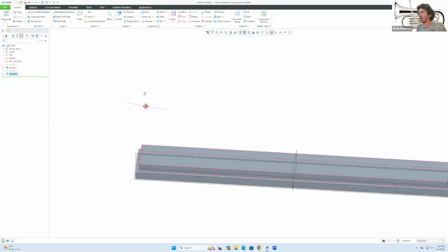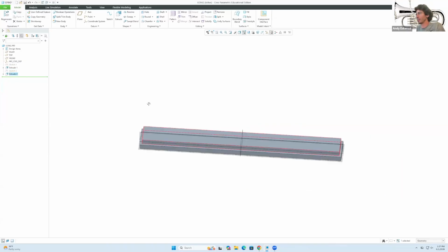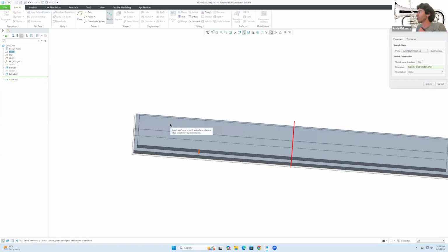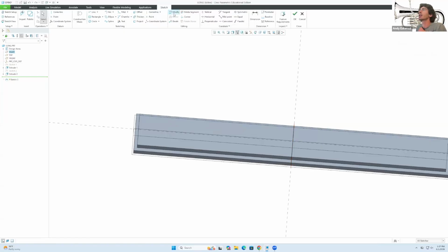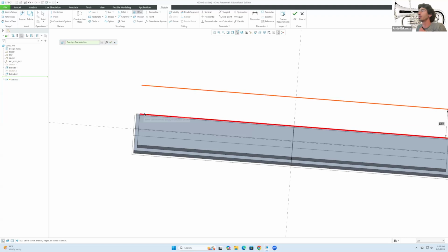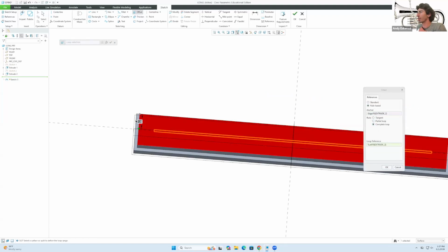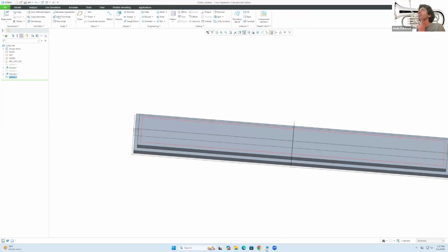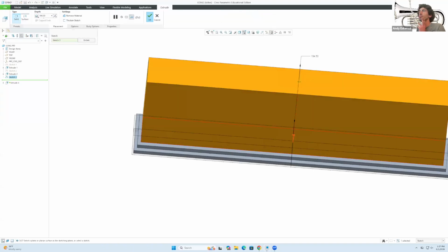So now we have our second layer defined, all nice and secure in there. Then we'll do chamfers and whatnot later on. But now I'm going to go back to Sketch, to this face, and do the exact same thing. I'm going back to offset entities, in here, selection, rule-based, complete loop. And I think, how much did we say, 2? Excellent. And now, okay, extrusion 5.